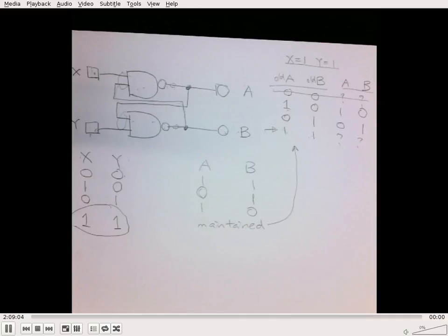The only way to simulate the oscillation is to change the source code of Logisim so that you can specify the exact latency of the gate, like how long it takes for an input change to become visible at the output. If you can specify that, then you have a chance of simulating the oscillation.